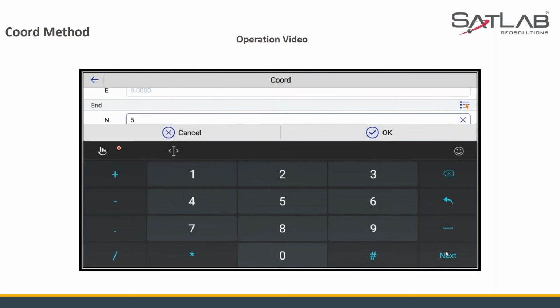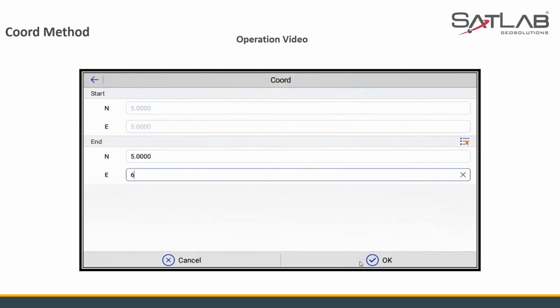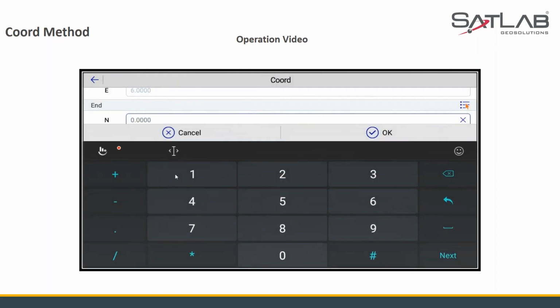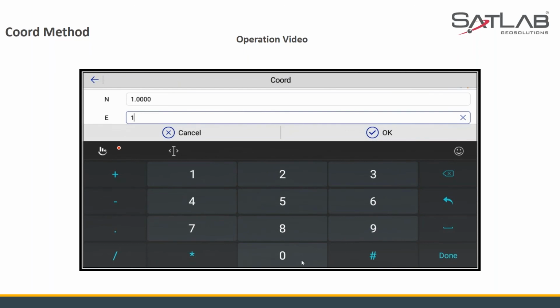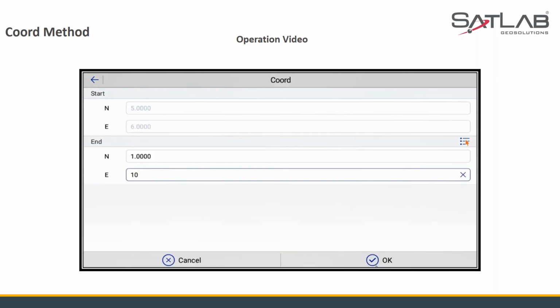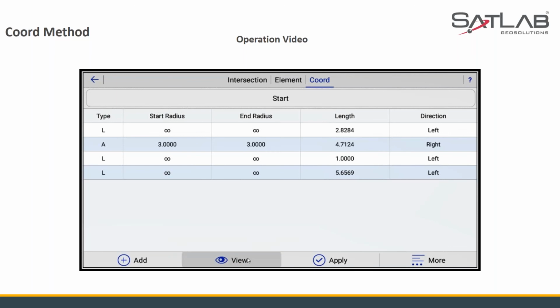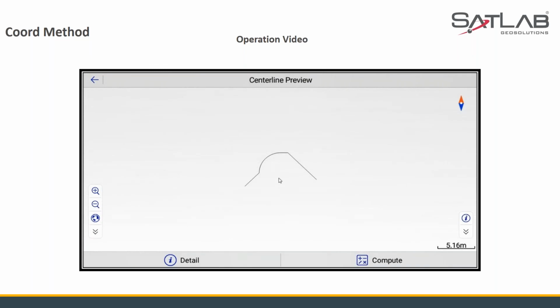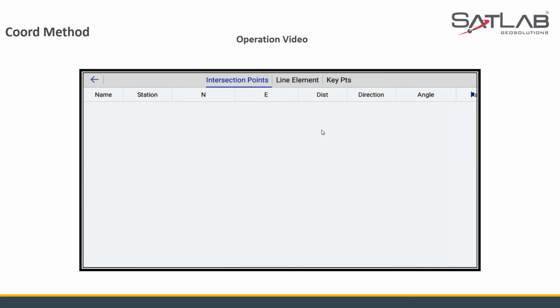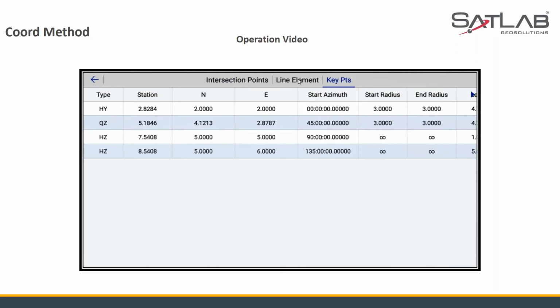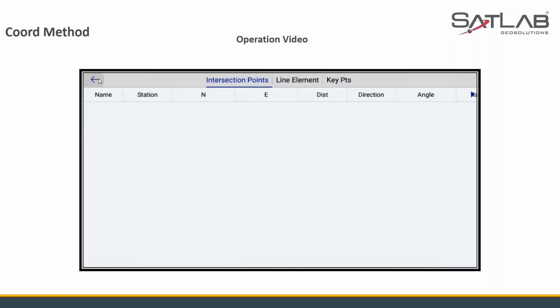I can use whatever I want. That will be the radius, of course. If I'm going for an arc, radius is 3, left to right. Then I can add another part, an arc or a line, depends. So it will automatically be phased as 5 by 5. That's it. Done. Line again.